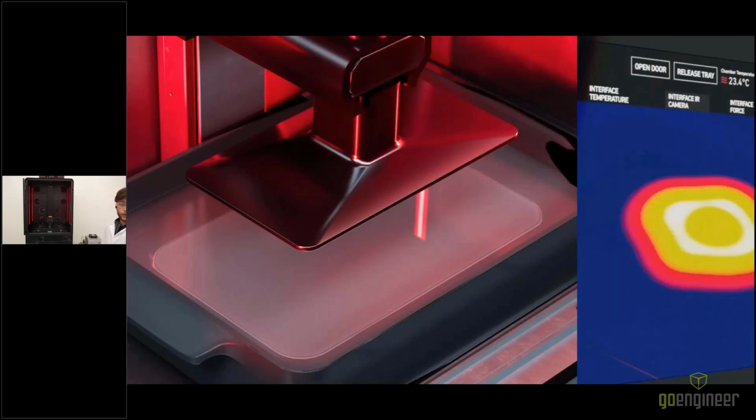The photopolymer cures where the light is illuminated. The pressure is released and filled with a positive pressure, creating a bubble within the vat. This reduces the printing forces substantially, enabling very large cross sections and very small features to be printed without the risk of parts becoming damaged when they are removed from that lower membrane.